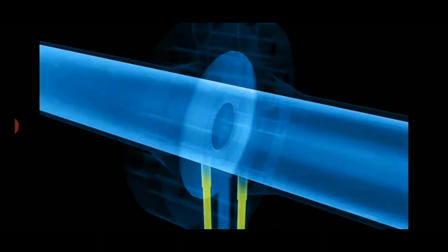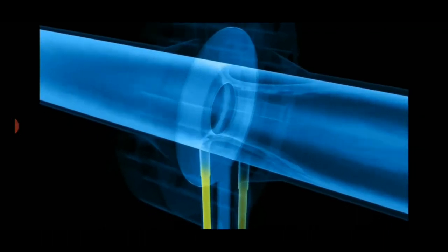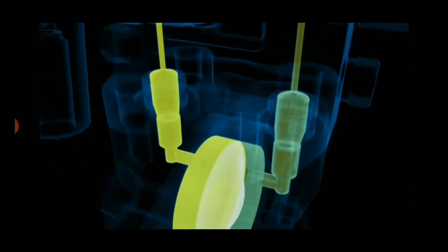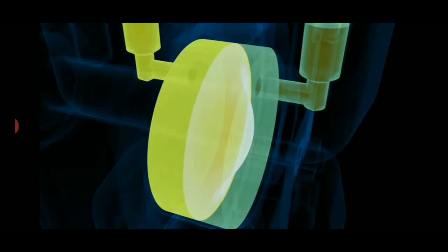Whenever the fluid flows, there is a pressure difference as the fluid passes through the orifice plate, and it creates a pressure drop in between those 2 points, which is sensed further by the diaphragm element which is mounted inside the DPT. It senses the differential pressure accordingly.